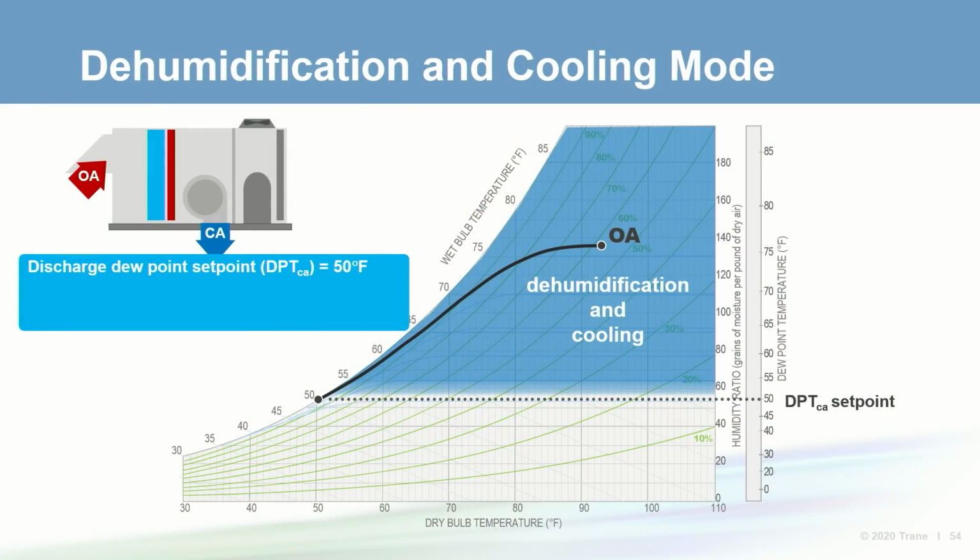This is also needed to account for the minimum turn-down capabilities of the equipment. For our example, this dehumidification mode will start whenever the outdoor air dew point is above 55, and then will not drop out of this mode until the outdoor air dew point drops below 52. For most comfort applications, this approach should be acceptable.